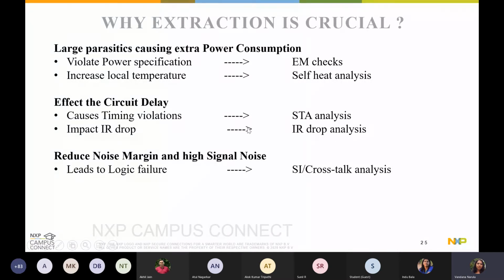We also have the IR drop analysis. The power rails could be causing a lot of IR drop. So when the designer is doing the physical design flow, they have to constantly check whether the IR drop is within acceptable limits and the design will function, or whether it is too much and the design needs to be tweaked to get better IR drop performance. And all those checks are carried out through the PDK collateral.